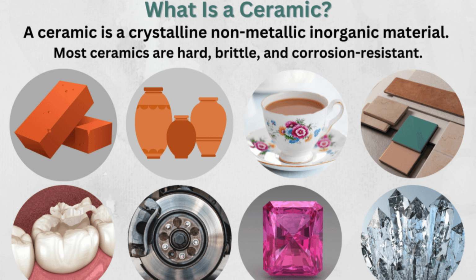Typical ceramic compounds include oxides, carbides, nitrides, borides, and silicates. Unlike metals, ceramics generally lack free electrons, making them good electrical and thermal insulators, while simultaneously exhibiting high hardness, exceptional thermal stability, and remarkable resistance to chemical attack.